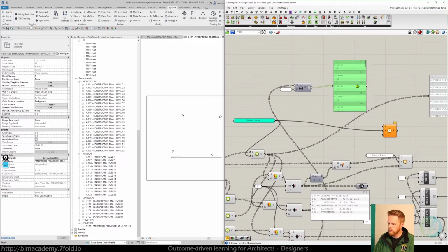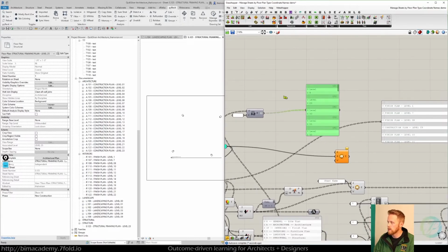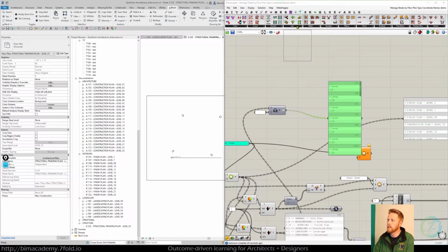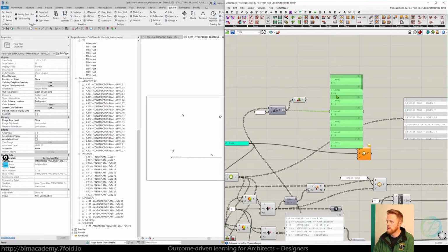So now I can start to format this information. Just to make sure, I can hopefully guess that this is going to be the index number 1. If I'm not sure, and I know it's always the last item in that list, I can make it a little bit more stable by grabbing the last index right here in Pufferfish. That's just going to go through every branch, find the last list, which in most cases is index number 1, and it's going to give me that information.